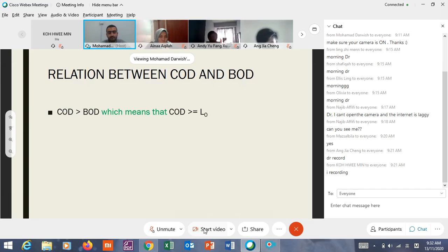L naught is the ultimate BOD, because BOD5 is less than L naught. L naught is the maximum amount of biodegradable organic matter. It means that if all the biodegradable organic matter is decomposed by bacteria, 100% decomposed, we will reach L naught. So this is the ultimate.